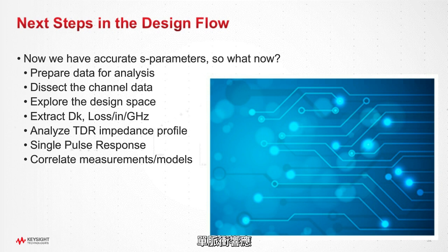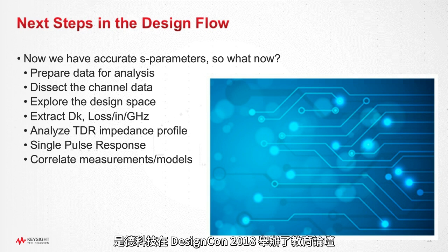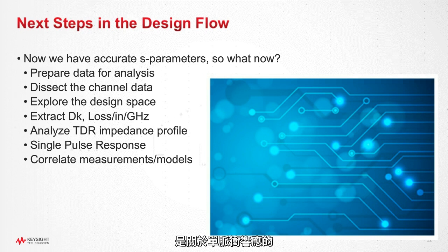Single pulse response. Single pulse response is another new emerging way of measuring our channels. Keysight Educational Forum at DesignCon 2018, we had a paper that was very interesting that you can get off the web about single pulse response. I think this is going to be very interesting because it basically is the blink of an eye. So whatever eye diagram analysis you're used to doing, you can see what one bit going through a channel will do.